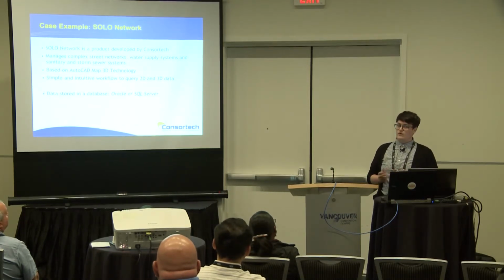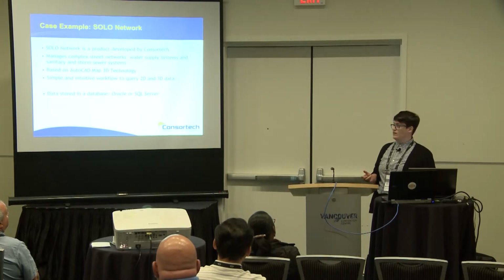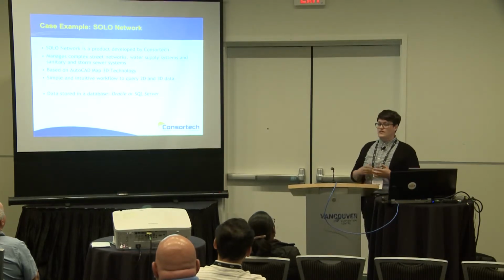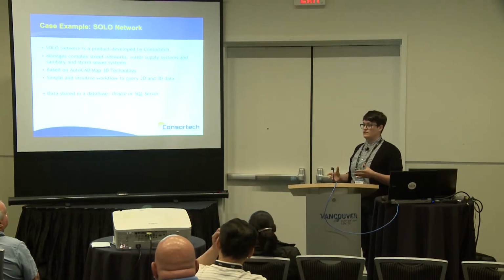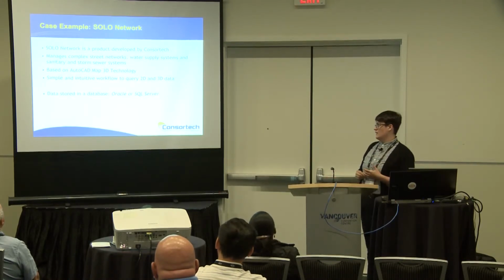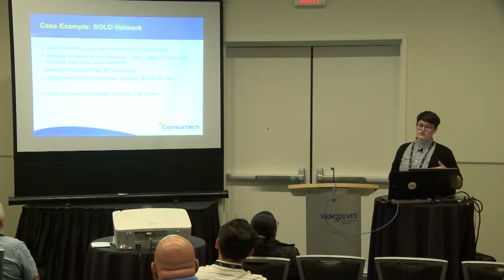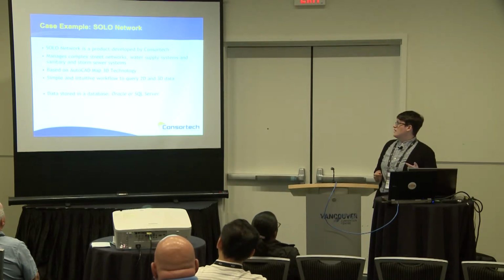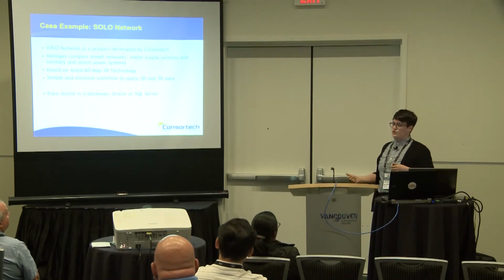As most of you probably know, in Quebec, we operate in French, and we have standards in French, et cetera. So we've developed a Quebec-specific template to manage infrastructure. And we have a number of municipalities who are using this internally. And we had to get them there somehow. We had to get their existing data into AutoCAD Map 3D. And this was the challenge that we took on with FME.